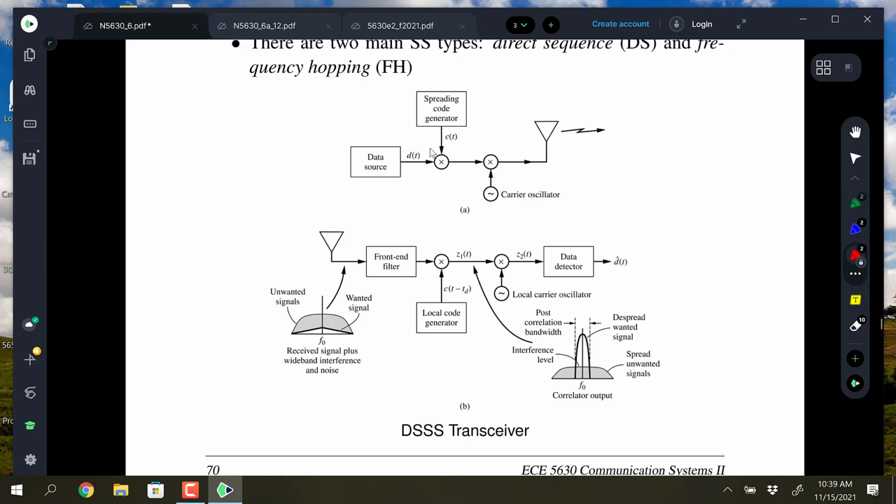So the way spread spectrum fundamentally works, and this is where I'm going to have to stop, is how it gets some of its main properties. When the signal comes in, and this is out of the book, that picture on the far left says that you've got a wideband signal, which is the triangle, and then you've got noise stacked on top of it. And the spread spectrum signal can actually sit below the noise floor, and you don't even know that it's there. That's the nature of UWB. You're not supposed to know it's there. It's not supposed to interfere with anything, like GPS, for example. And then you have the local code that comes along at the receiver, and it will be synchronous with the spreading code once you lock onto it with a despreading algorithm.